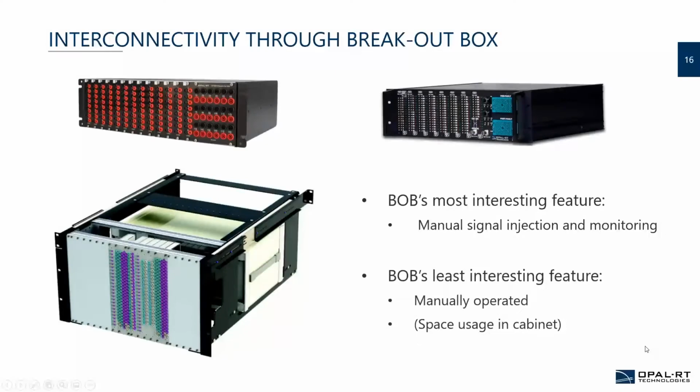The next step is the manual breakout box, which is a little bit like the fault insertion unit in a sense that it permits you to do the same test. So you can manually short two wires together and insert different types of noise signals. For example, you want to validate the impact of the injection of a 60 hertz wave on the monitoring of the alternator generated signal. So you can send a signal manually through the breakout box. That's the cheaper counterpart to the fault insertion unit.